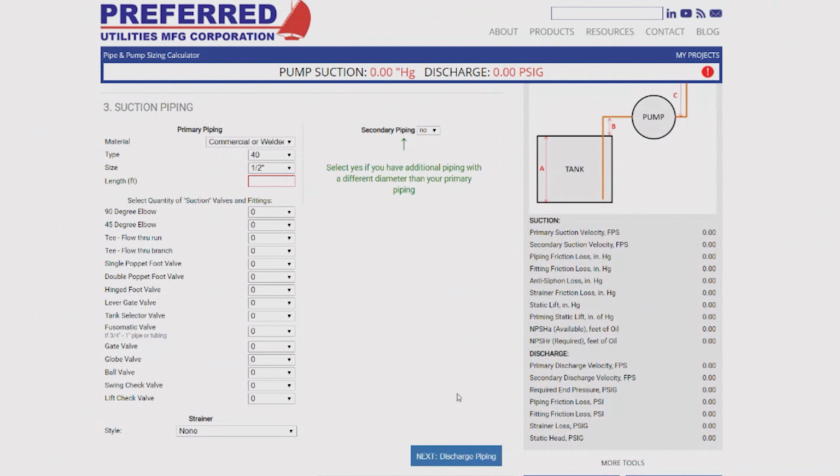Also, for your day tank controls, if we have a large plant with multiple day tanks and multiple generators and it's seeing the full flow of that transfer pump set, there are cases where on smaller day tanks, depending on where you're located, it can overwhelm the level controls. So we'll want to limit flow for that case as well.